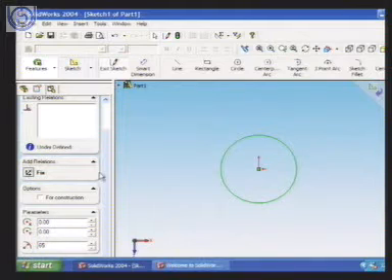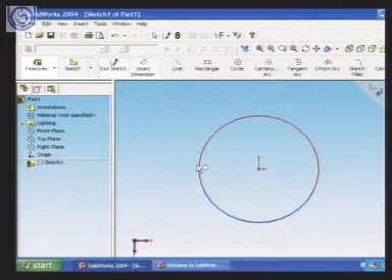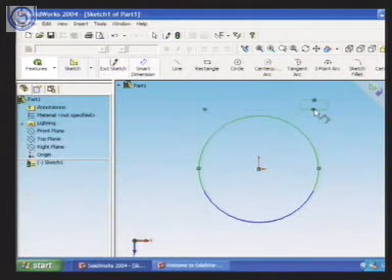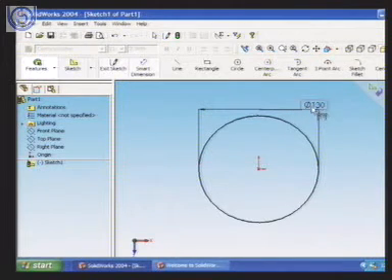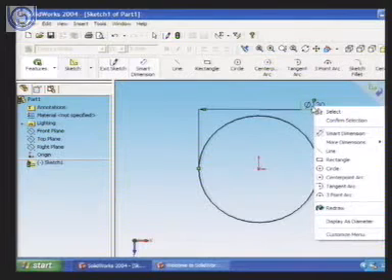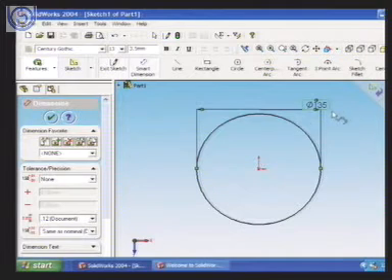65. Okay. Or I can change it from here. So diameter is 130. If I double click it, what happens? I am getting this dimension. Suppose I change it to 135. So the dimension can be changed from here also. We have the smart dimension option. We have the option from the menu on the left side. So you can change the dimension from both sides.